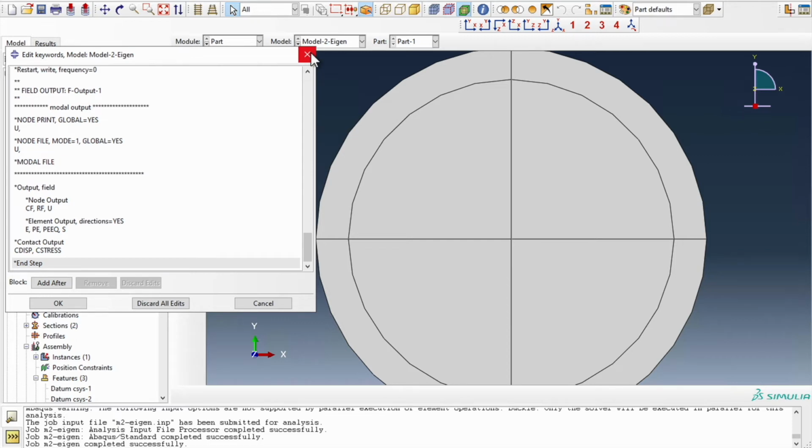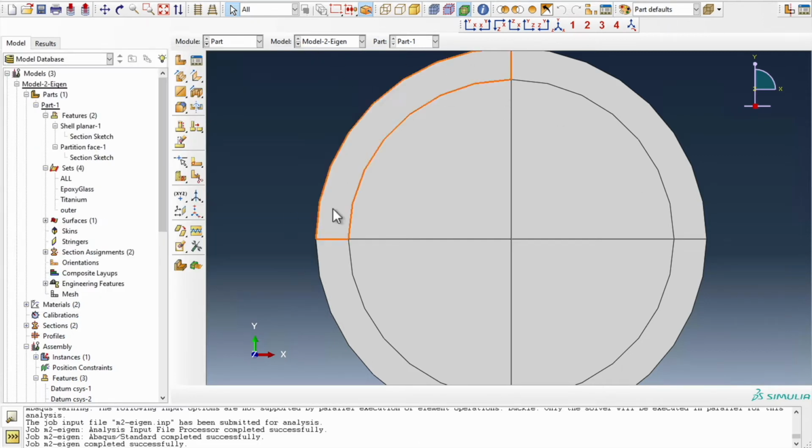So this imperfection is actually important to model. Otherwise, since we are doing a numerical study in a very ideal condition, there is no inherent imperfection in our model. If you start compressing this shell, you may find that it keeps on compressing because we are considering a linear elastic material model, and there is no buckling, right.